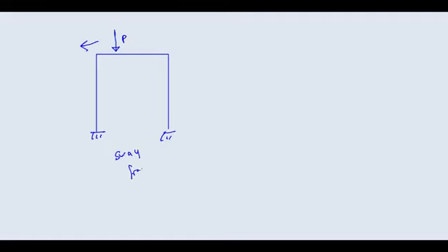On the contrary, if you have a frame like this, and suppose my load is acting here, instead of at the center, definitely your frame will sway in this direction. So this will be your sway frame.